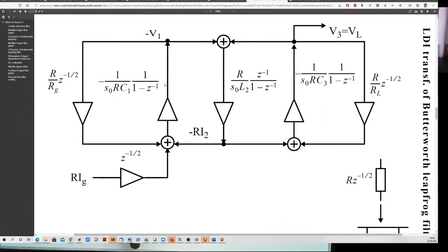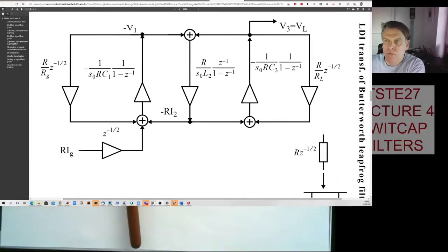So pushing the halves to these branches and then combining them to the following system. Okay, so I have now my integrator or accumulator that we recognize from the first hour, one of them with the switches in a certain position and the minus. And then we have the other one that I was referring to with the delay and no minus. The other version of just flipping the switches back and forth. So you just move the switches accordingly.